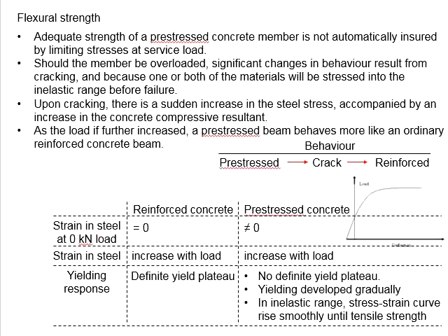The actual loads acting on the member may be higher or lower than the specified load. Also, some loads are by nature imposed loads, which can be there and sometimes are not. Because of that, the actual load acting on the prestressed concrete member is not constant throughout its service life. It is more likely to fluctuate over time during its service life. Sometimes the member may be subjected to critical loads. Sometimes there is no imposed load acting on the member.